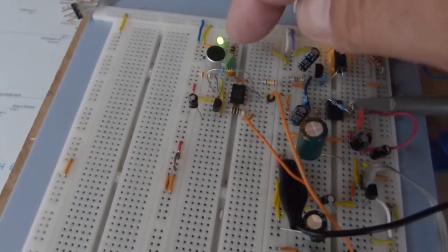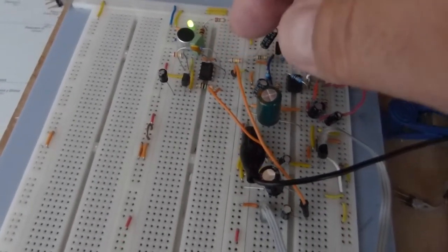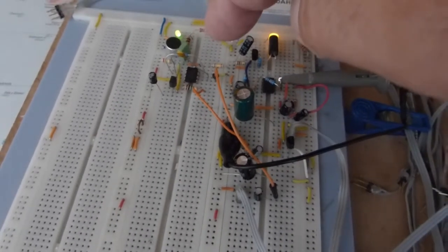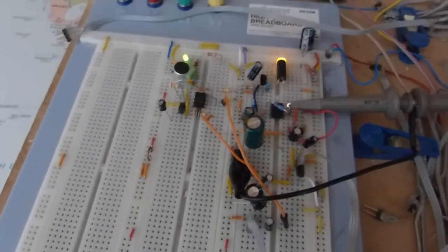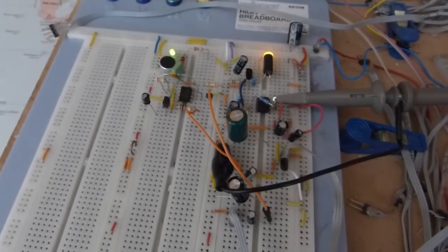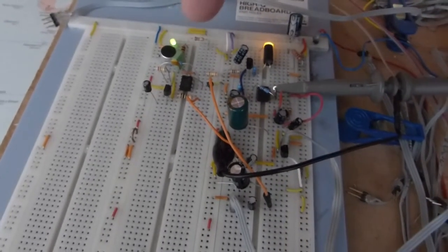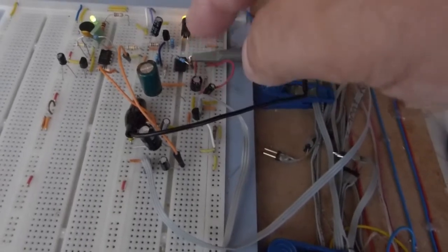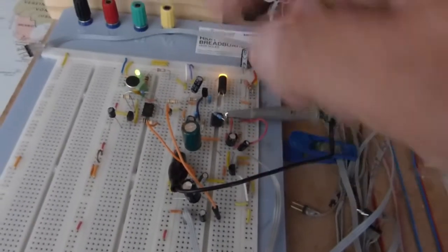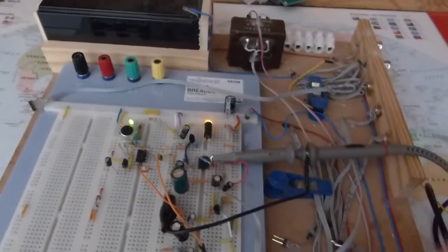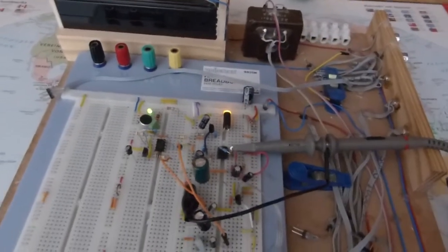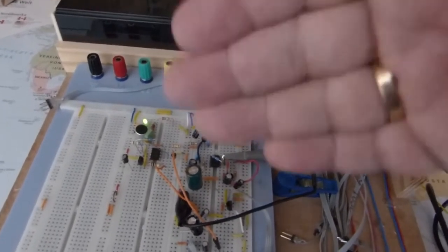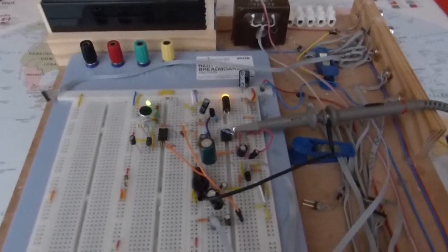And here we have a simple condenser electret microphone with a preamplifier and a stage with something like a voltage controlled amplifier. It means that the amplification of the stage is controlled by the impulses generated by the random generator, so that the amplification goes up and down in the rhythm of this random signal. This is causing the modulation I told you about.